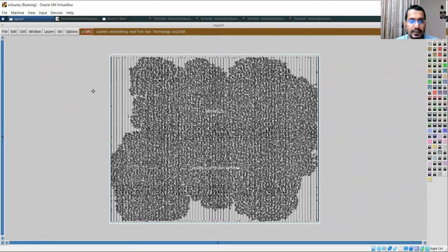And before we conclude this lab session, I would like to point out that this power distribution network, that is the power ground network, gets created during floor plan. That should be created during floor plan, but in OpenLane flow right now the order is a little different. So the floor plan does not create the power distribution network.